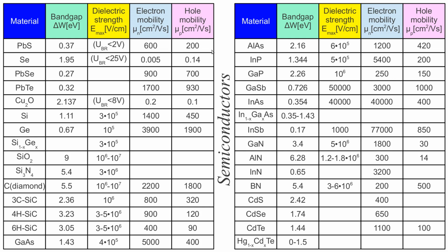Yet another fact when we build our devices, and especially transistors, so this will be more important next time, is to check the electron mobility and hole mobility. Both define the speed at which a semiconductor device may work. If the electron mobility is higher, we'll prefer to use electrons in our device. If the hole mobility is higher, we'll prefer to use holes. You see that for silicon, electrons are about 3 times faster than holes, and in fact, N-channel transistors, most transistors, are 3 times faster than P-channel transistors.